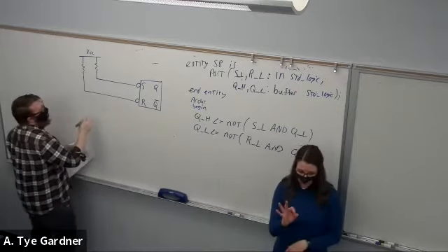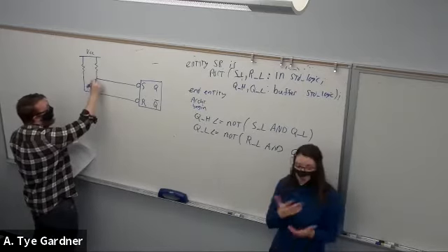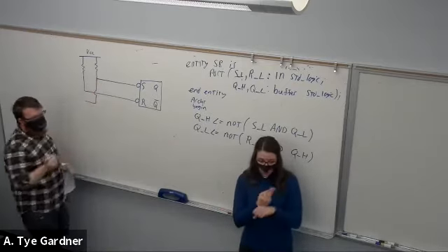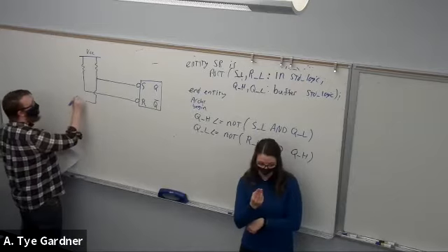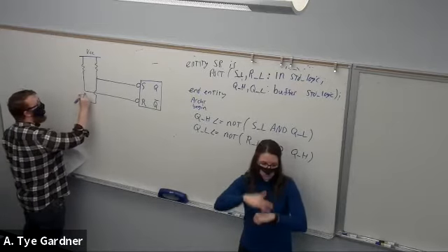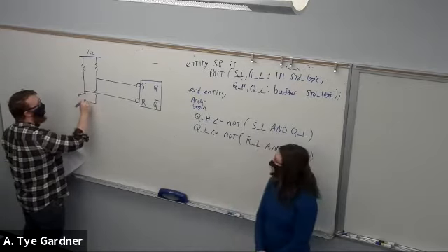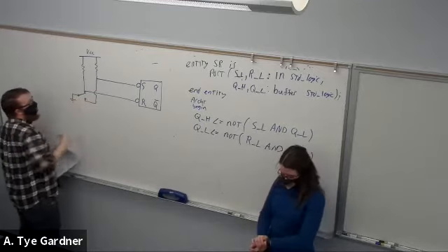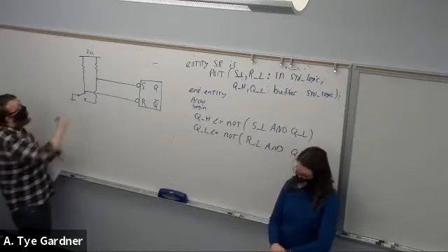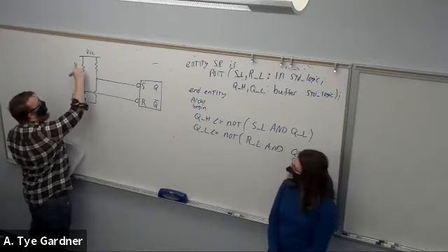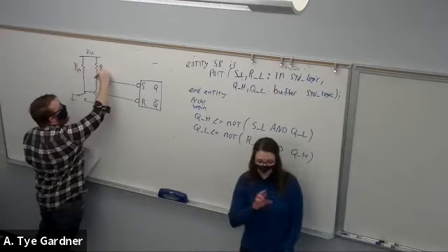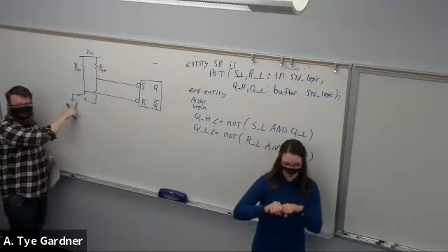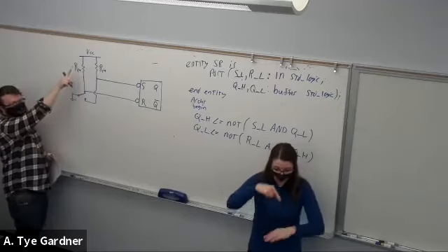And we want to be able to use a switch to connect them to ground. Okay, remembering that these are our pull up resistors, if we're not connected to ground, the resistors will pull it up to VCC.